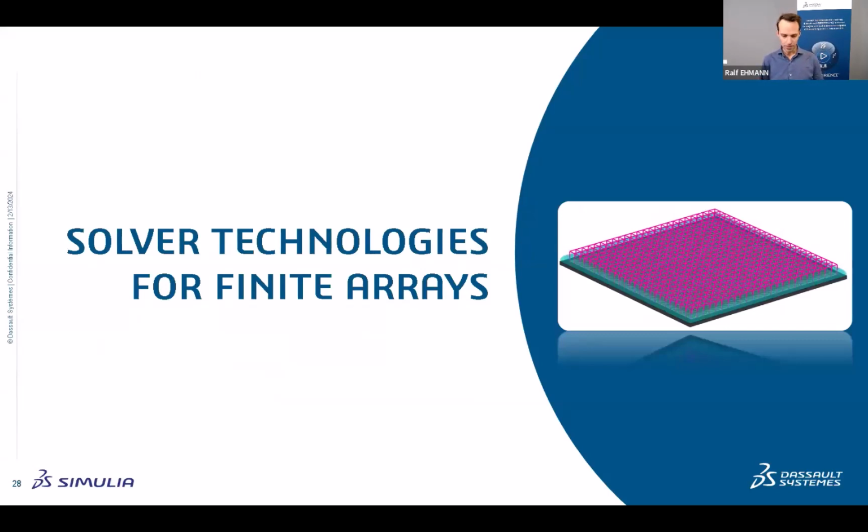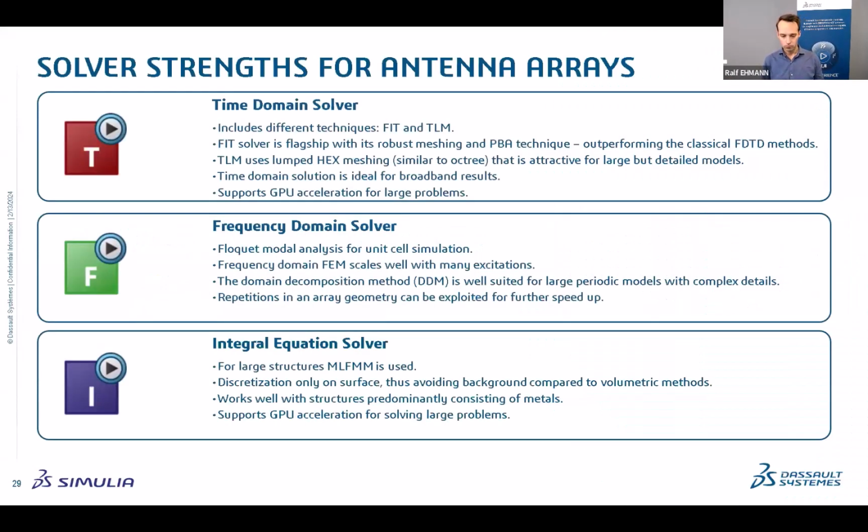So this brings me then to the solver technology, because it's one thing to automate the setup, modeling, everything. It's another thing to actually solve these really large problems. And as you know, CST Studio Suite has many different high-frequency solvers: time domain, frequency domain, and integral equation. When it comes to the time domain solver, it has 2 different methods. One is the finite integration technique, or FIT, which is really our flagship solver, and it's very robust with a PBA technique that it uses.